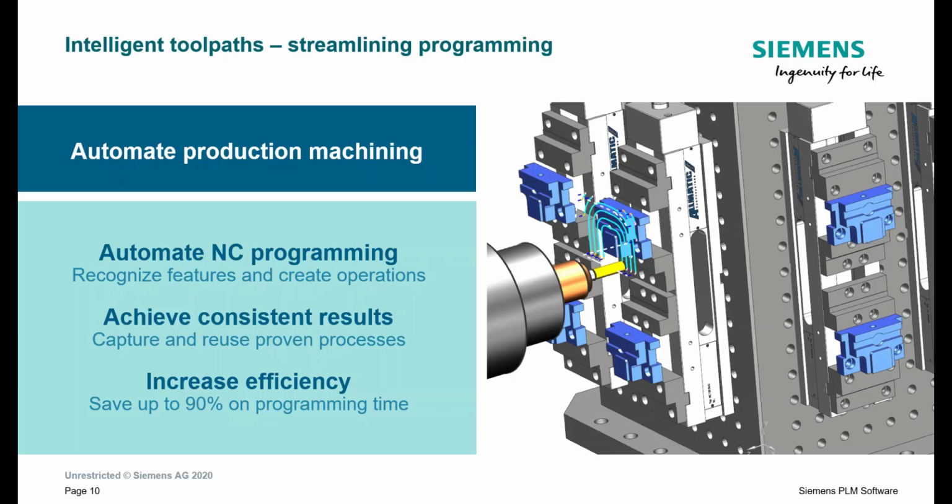Multifunction machines let you make parts using milling, turning, and drilling in one setup, which can reduce the machining cycle and improve accuracy. These complex machines can be challenging to program, but you can use the advanced tools in NX to simplify the process. You can visualize and control the machining sequence across multiple channels using Synchronization Manager, and the system keeps track of the in-process workpiece, providing seamless transfer of the workpiece between milling and turning.